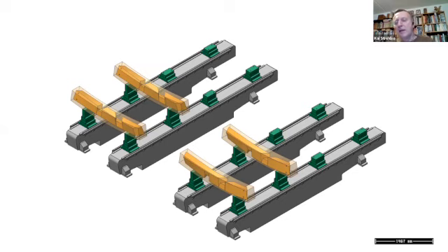The same applies for CLT and for panels, but when we talk about freeform structures, it's a completely different story, because you cannot produce freeform structures on these Hundegger machines, since they can only produce sticks or panels, and you don't have software for it. So the first three freeform projects were all built with Mastercam, SurfCAM, PEPS, all these kinds of CAM systems, which are also used for the automotive industry.